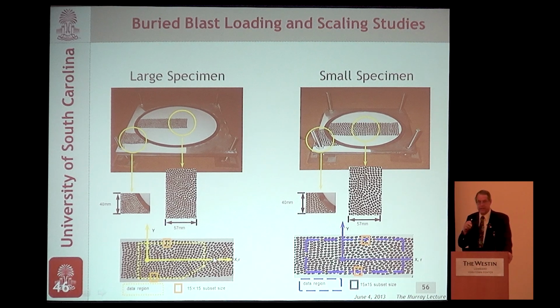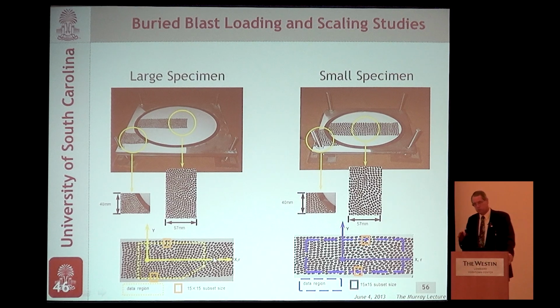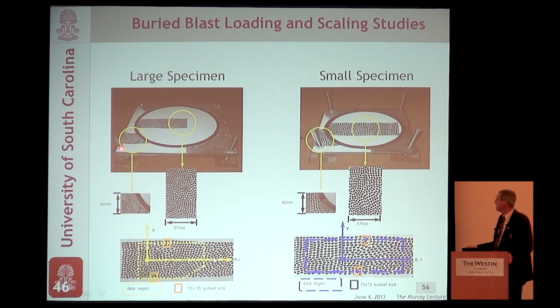We kept it fairly damp before we ran the experiment so that it wouldn't delaminate. That's one of the issues you have to deal with. Delamination does occur at the high rates, and things are pretty well bonded, and they don't have time to begin to delaminate before you start the experiment. We also measured on the frame itself. We're also interested in the rigid body motion of the frame, as well as the deformation of the plate inside. And those are used to extract information about the global energy transfer.